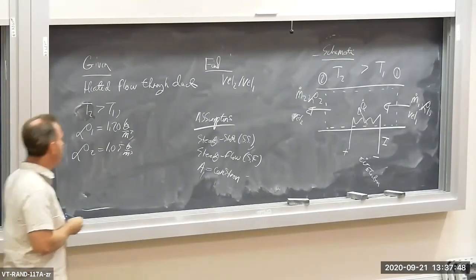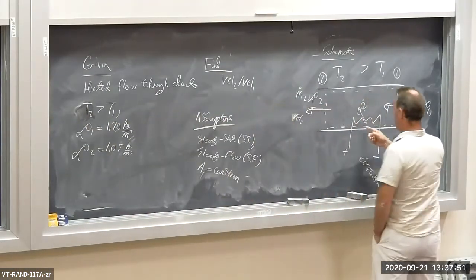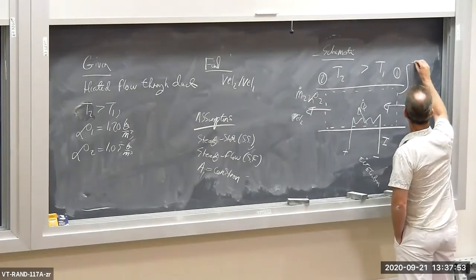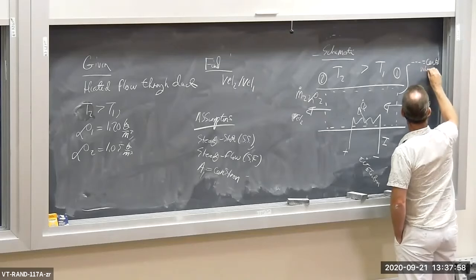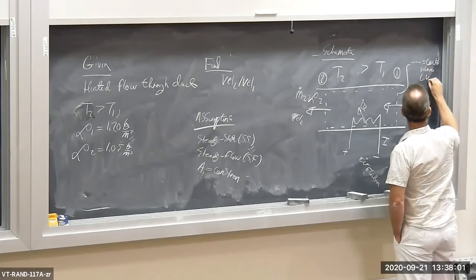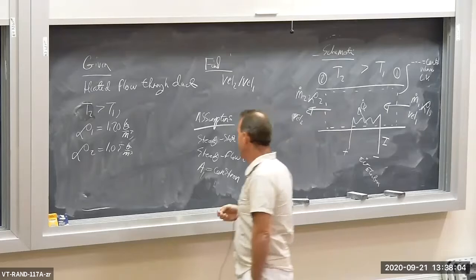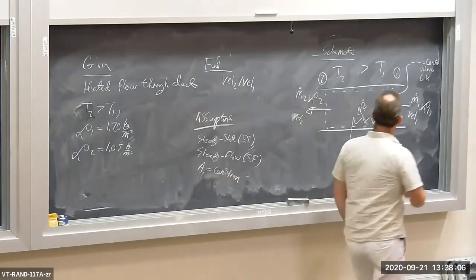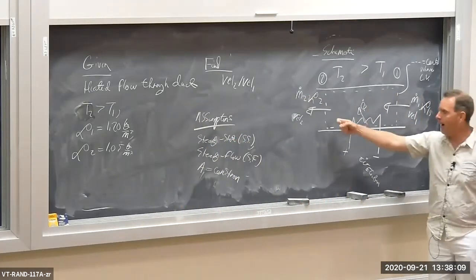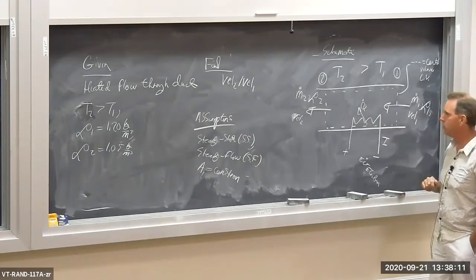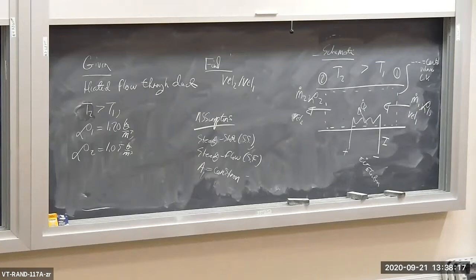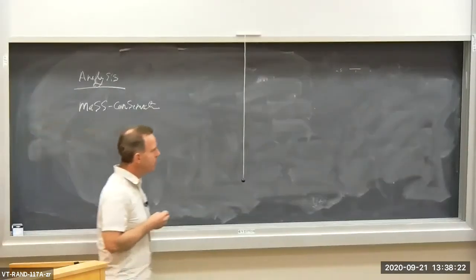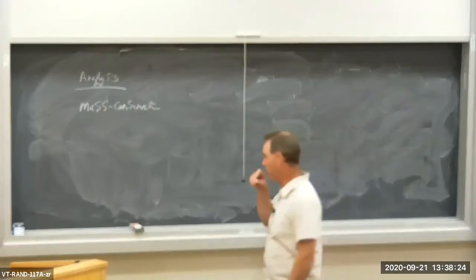The dashed line here is my control volume. So this dashed line is the control volume, or if you like, CV. It's my control volume on my system. It's clearly an open system because we have an inlet at location 1 and an outlet at location 2 in which mass passes across the system boundary. This is not a closed system. This is an open system. So we can apply conservation of mass to this open system and see what we get.